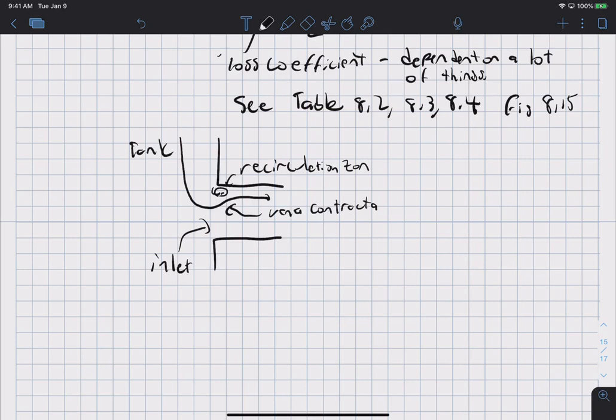So the vena contracta sort of reduces the actual flow area because the streamlines are going down and around, and there's no net flow going through this region here. And there's another vena contracta down here, so I'll just get rid of this inlet thing so I can draw the streamline.